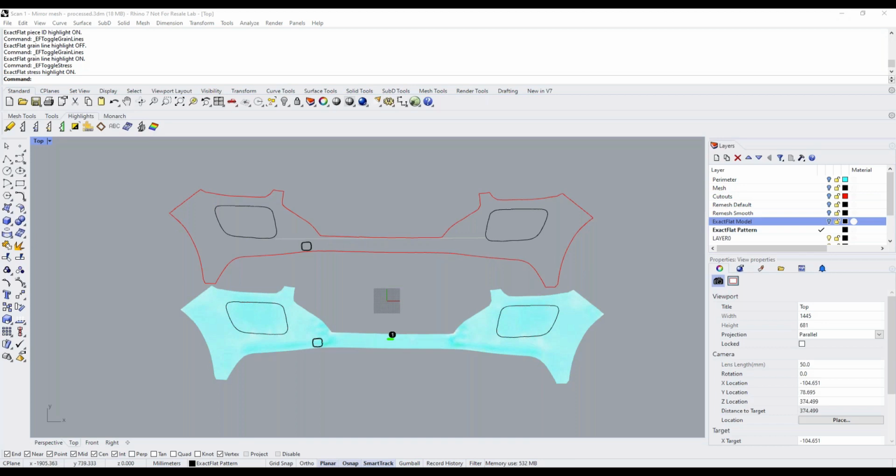All right, look, I just want to clarify for the audience out there. So you can decimate in the Peel software, but that is not recommended. You want full fidelity of the mesh coming out of Peel. Is that correct? Yes, correct. And then when you get it into ExactFlat, then you can condition the mesh using the ExactFlat tools to make it optimal for creating a flat pattern, right? So prior to ExactFlat, let the mesh be, use all the detail. And this is also one reason why you don't want to overscan. Overscanning essentially adds more polygons and complexity to your mesh. So it's another consideration here.